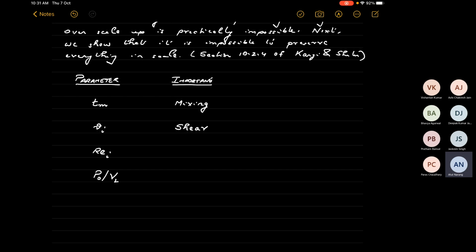So the type of reactor that I have shown is rarely used in mammalian cell cultures. Many of the reactors actually have no impellers at all. They either work on bubbles, simply dispersed like an aquarium through the reactor, and even those cannot be sent at a high rate because the cells often attach to the bubbles. They lie at the bubble-water interface, and when the bubbles come out, the cells just tear apart.